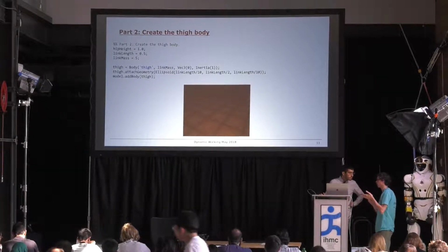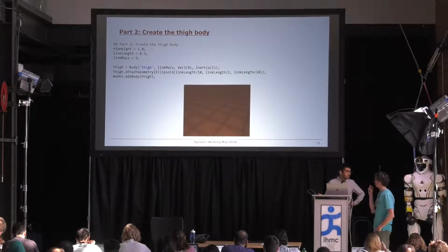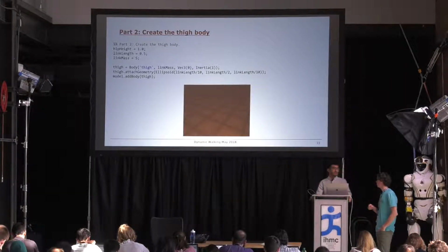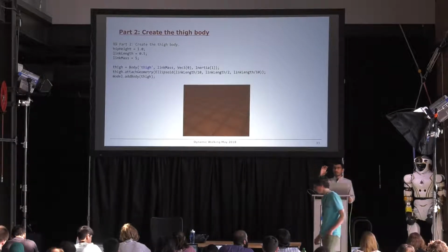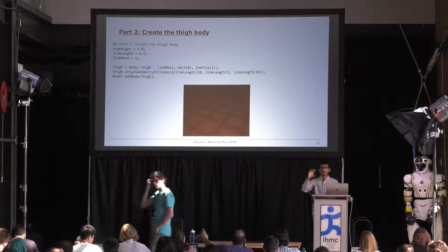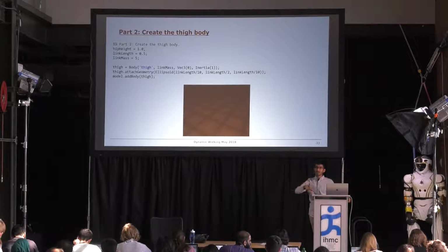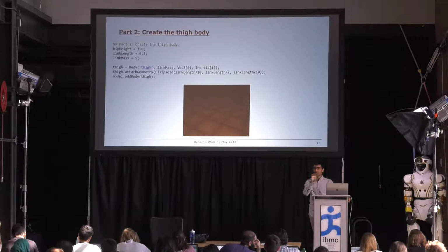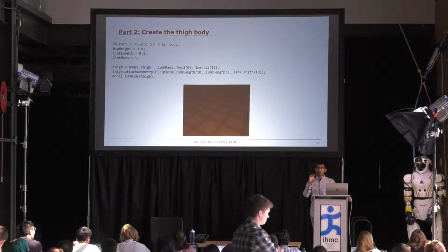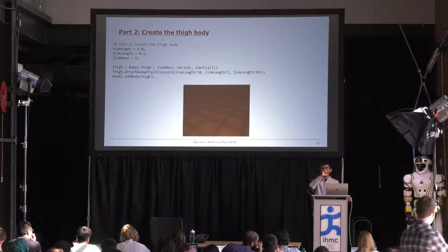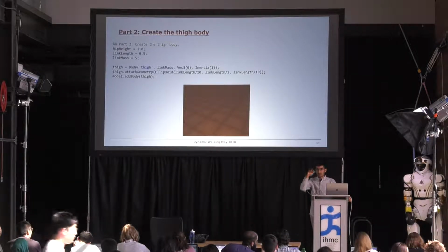Antoine just told me some people are running parts of the script block by block. I know in Matlab you can select a portion of code to run and just run that portion. But in this case, just run the entire script every time. Don't run the script block by block. The reason for that is that when you run block by block, Matlab doesn't know that you want to have the import line to import the OpenSim libraries that you have at the top of the script. So just make sure you run the entire script every time.